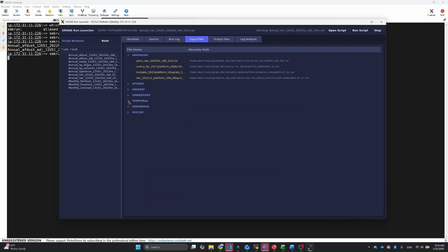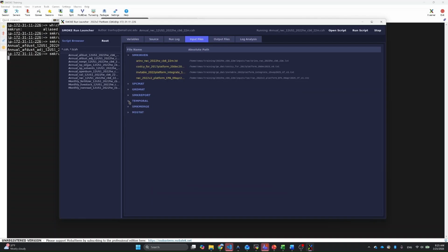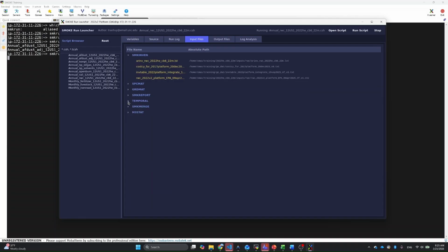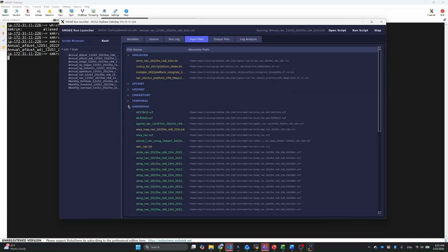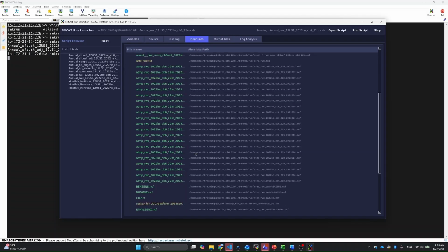Then Temporal was run after Smkreport to generate temporal allocations, which is to go from annual emissions into hourly emissions in SMOKE output. And following that, into Smkmerge. This is the main program that merges all of the intermediate output files generated from previous SMOKE core programs to generate SMOKE output in the ready format that a photochemical model like CMAQ can use.